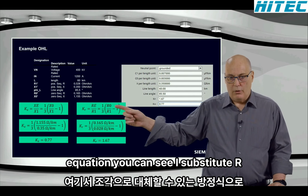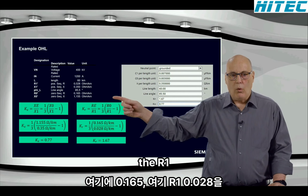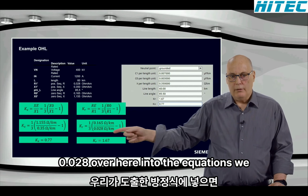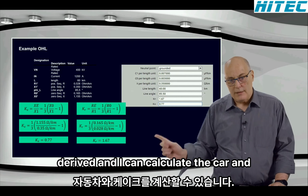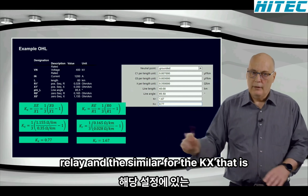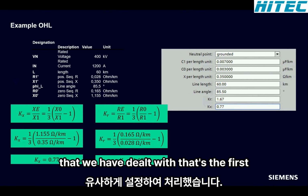You can see I substitute the R0, which is 0.165 over here, and the R1, 0.028 over here, into the equations we derived, and I can calculate the Kr and Kx, and then I would set that in the relay, and similarly for the Kx, that is that setting. So that we have dealt with, that's the first one.